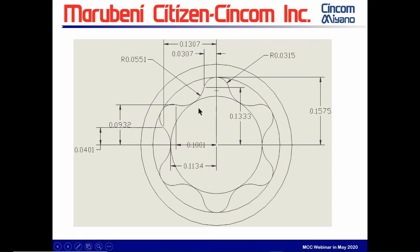So you would have those numbers, and just keep using them all over. I mean, this is going to be the same 30 there, and you just generate the radius going back and forth like down the outside. Same story as the inside, but you do have to have a cutter that has smaller than 031 radius because you can't generate a radius smaller than the size of the cutter. So if you use an 031, you more or less would go to center and come back out. So the look on the inside would be more like something like that instead of generating a radius on the bottom if you use an 062 cutter. If you use a smaller, you would generate. But that's just to give you a view of it.